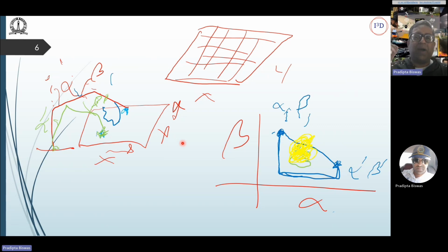And often it has multiple solutions instead of a unique solution. So in this next set of slides, we will look at a simple robot with only two joints, which we represent by alpha and beta, and we represent the configuration space in 2 dimensions using this alpha and beta. If we can solve any motion planning in this alpha beta space, it will give me a series of configurations by which I have to take the joints, and the result will be that the end effector will come to our desired position.